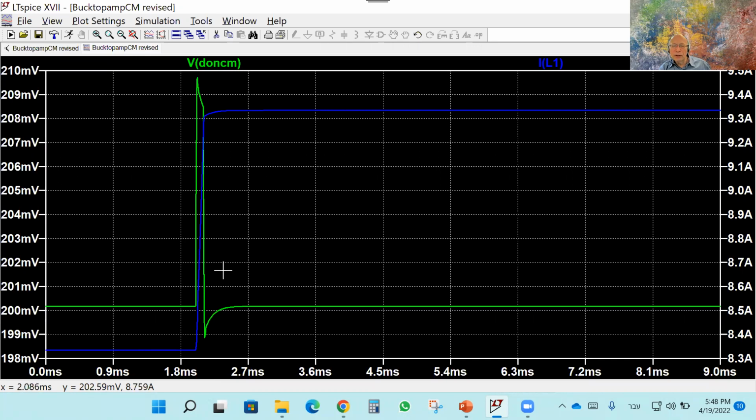The duty cycle does not change very much because the output is still the same output. We've seen that there is a small disturbance at the output, but then it's kept at 10 volts also. So you can see all these very nice features and very accurate behavior in a comfortable way. Obviously, if you have a real system, you can probe with the oscilloscope and some differential probes, and look with a current probe. But here you can do it very nicely.